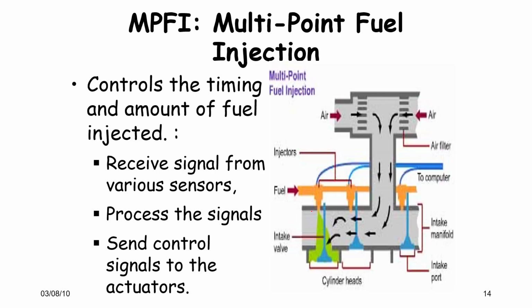So, what we will study is how these individual systems are designed and how they communicate over a network. So, coming to the multi point fuel injection system, what you can see is that this is a multi cylinder engine. Fuel is being injected into the engine via an intake valve, and this is the airflow. So, air is coming in that way. There are computers which are controlling how much fuel is injected. That determines, of course, the output of the engine in the sense the torque it generates. And furthermore, you would like to balance it in such a way that you generate the maximum possible power with the minimum possible fuel and also reduce the vibration, because the vibration is a function of how much these pistons move. So that's the reason there's a need to receive the signals from various sensors, process them, and again send signal back to the actuators, in the sense the actuators would control the amount of fuel.